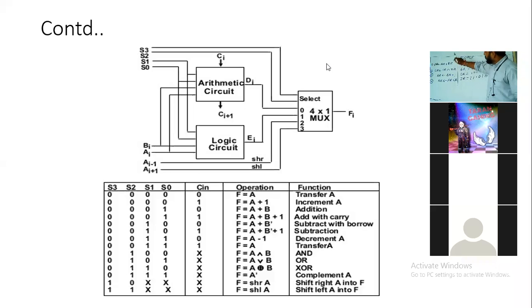First operation is addition: add the content of register AR with the content of register BR. Second, perform logical AND operation of the CR register with the DR register. Third is the increment operation: increment the contents of the BR register. Next, perform the subtraction operation.